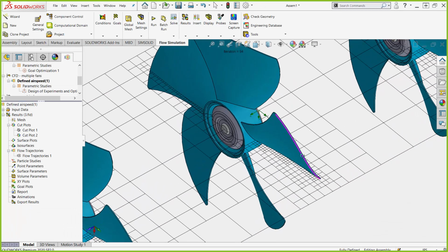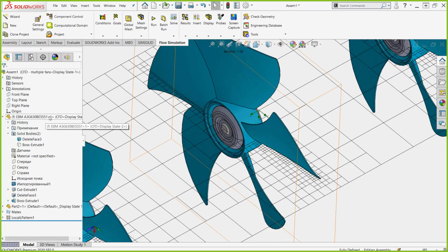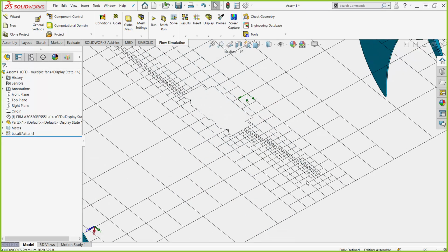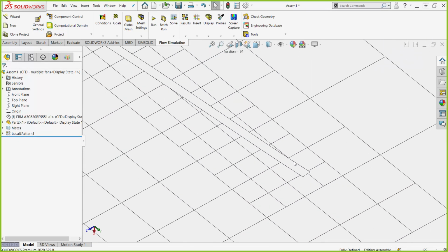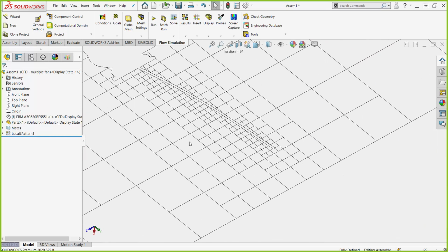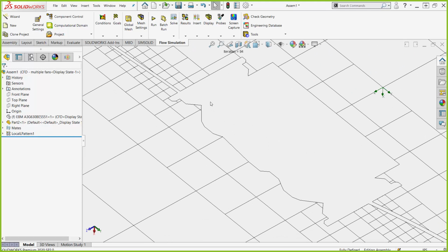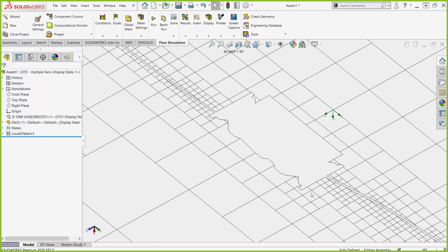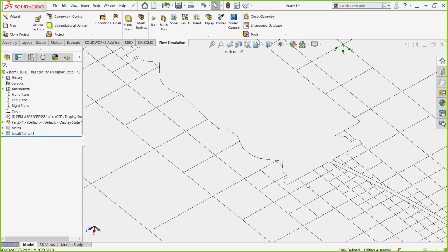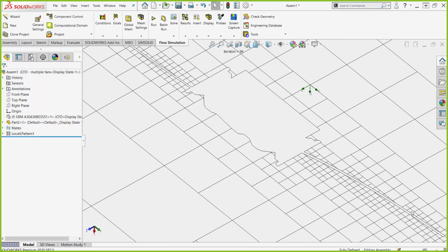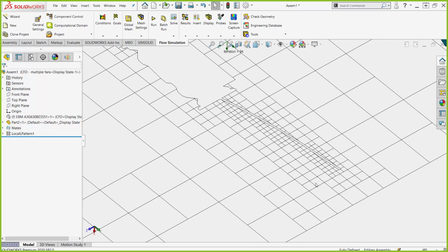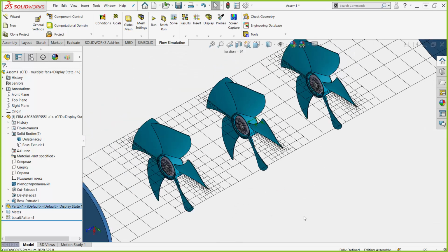So hit OK. I'm going to go ahead and hide this fan again so we can get a closer look. And as I zoom in, I can see that that shape is very smooth along that fan blade. I did capture that region well enough. Where there tend to be problems in general, fillets, round faces, especially swoopy faces like that, so I'm glad we did that mesh refinement. Does this match the 4 to 5 cells across the thickness that I asked? Yes, it does. I have over 5 for sure, so I've met my minimum. My crash course in the meshing.